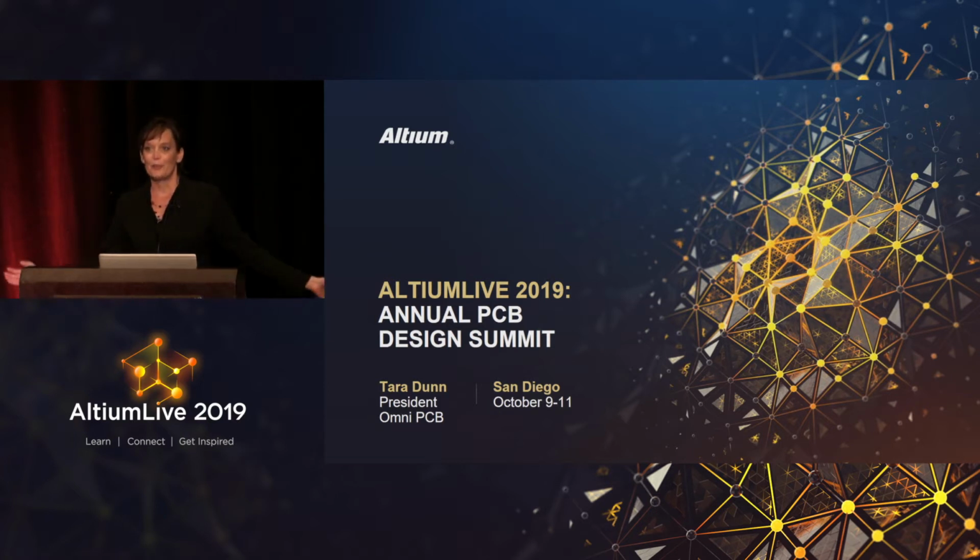So finally grabbed my entire team of very smart engineers that I was working with, and we went up to the customer's facility and started looking at the flex in use. And it was just a nice, gentle bend. There was nothing that you would think would be causing these kind of problems until suddenly somebody stopped and said, hey, wait a minute. Instead of it bending like this, it was bending like this with a little tweak at the end. That tweak was cracking all of those traces. Very simple fix.